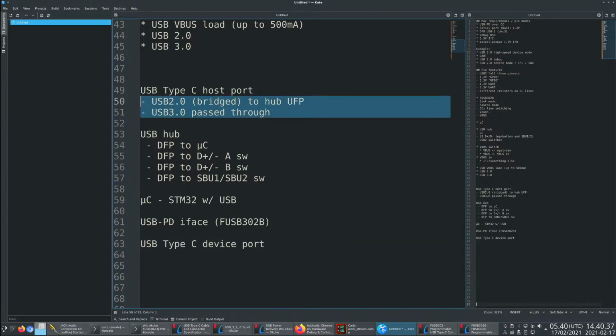And by the way, one point here is that because this is going to be a dumb USB 3 device, effectively, if you plug in a Type-C to Type A USB 3 cable, that's going to work fine and give you all the features. The only question is that depending on what's on the other end and how the SS pins are passed through, you might have to flip it around to get on the right SS pins because there's going to be no mux here. But again, because this is a test tool, I'm okay with telling people you have to flip the port over for some use cases. Some Chinese devices do this too, and it's really lame for a normal consumer device that you have to try both ways. But again, for a test tool, I can deal with it.